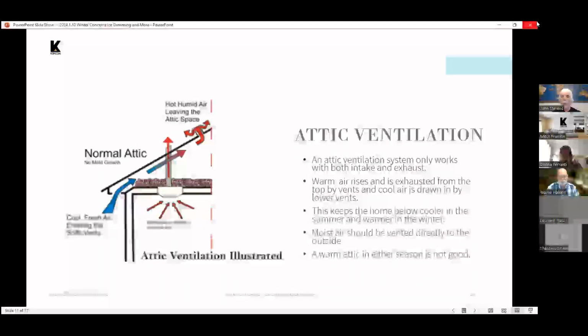Another important thing in preventing or minimizing ice damming, and also just generally for the health of the attic space, is that any fans in the living space, either bathroom or kitchen exhausts, need to be vented directly to the outside so that the warm, moist air coming out of either a kitchen or bathroom will not accumulate in the attic and cause problems with deterioration.